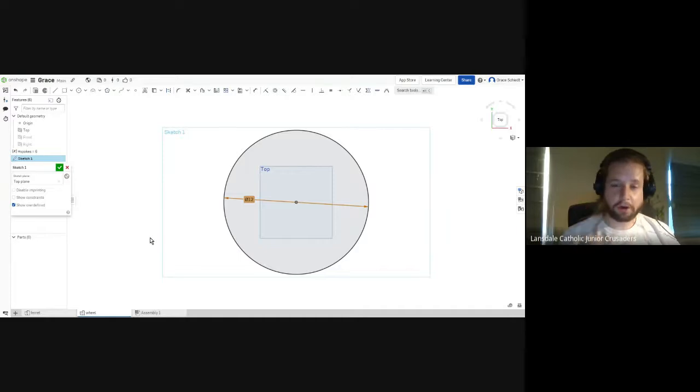You can use the offset function, which will take whatever geometry you have and offset it either inwards or outwards. If you scroll up, do you see where the scissors are? Yeah. It's right next to the scissors. And it is the O key. So I want you to click that line. And then do you see the little arrow key that exists there? Yeah. Let's offset to the inside instead.